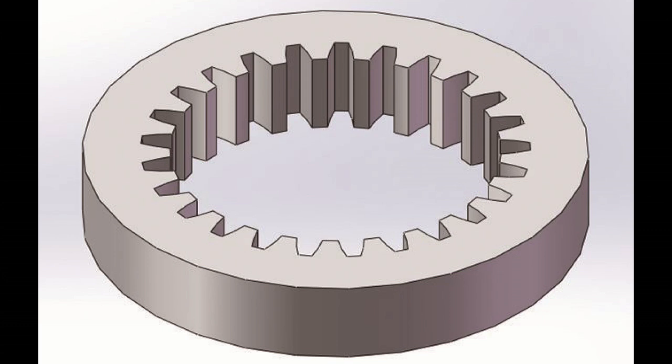Shaper cutter overstroke. When generating internal teeth using a gear shaper, ensuring that there is sufficient clearance at the bottom of the cutter stroke width is crucial to prevent insufficient tooth depth, chip packing, and other manufacturing problems. Another critical application is shaping in a blind hole. How much clearance below the face width is needed?